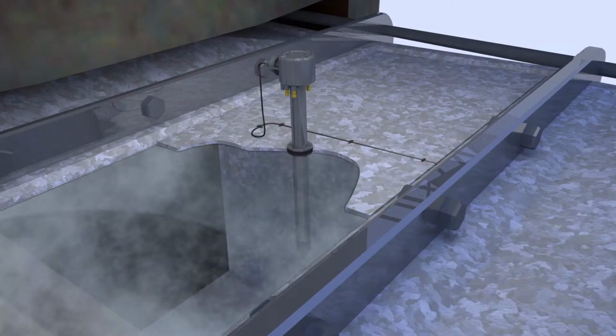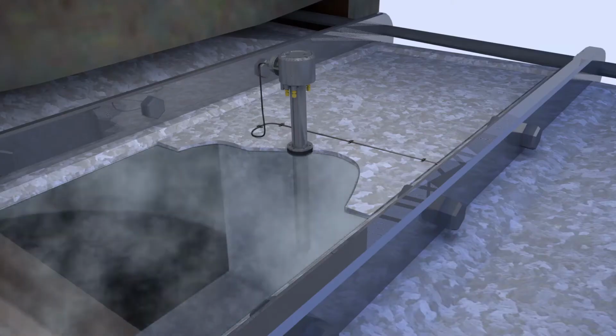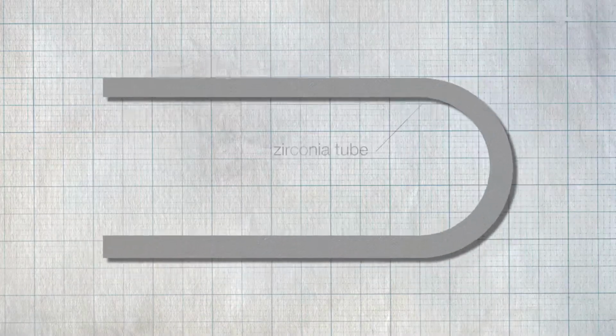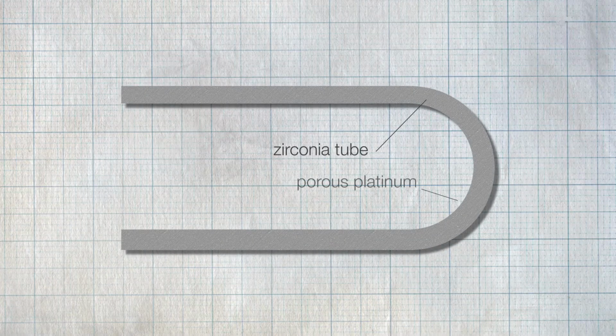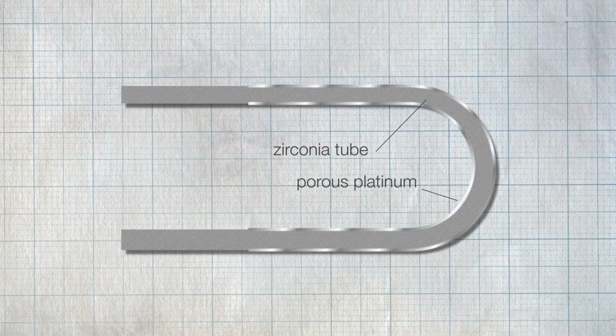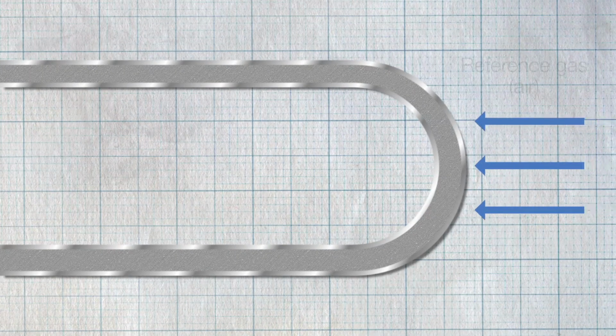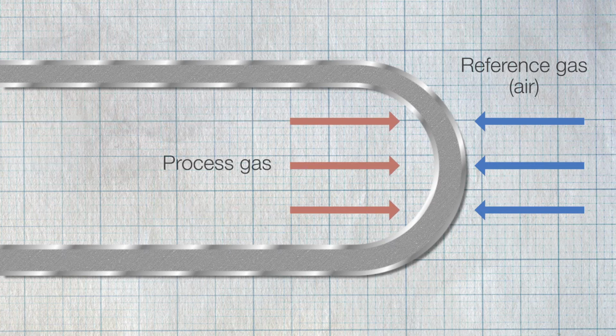ABB's AZ Oxygen Analyzer sensors use zirconium oxide sensor technology, which produce a reading of the net oxygen remaining after the combustion of all the available combustible gases. The sensors consist of a thin piece of zirconium material. A supply of air is applied to one face of the sensor as a reference gas. The process gas being measured is applied to the opposite face.